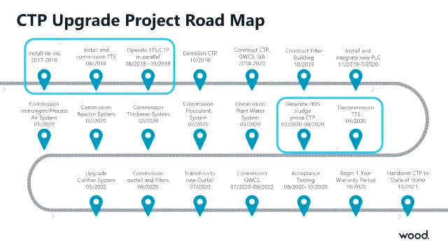The other key point where the temporary system fit in and tie-ins included getting through construction of the treatment plant components itself, and then being able to start up the new CTP, generate high density sludge, again, with that temporary system in operation in parallel if we need it. So we could commission and implement the new CTP in a controlled environment. Once we prove that process, then we could come in and demolish the temporary treatment system and finish closing out the project with some of the upgrades that could be done kind of on the ancillary or the exterior of